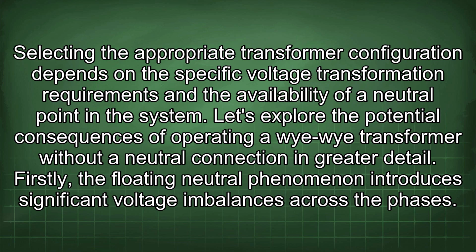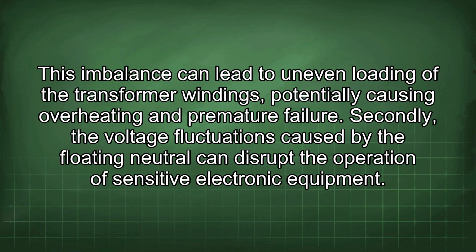Selecting the appropriate transformer configuration depends on the specific voltage transformation requirements and the availability of a neutral point in the system. Let's explore the potential consequences of operating a Wye-Wye transformer without a neutral connection in greater detail. Firstly, the floating neutral phenomenon introduces significant voltage imbalances across the phases. This imbalance can lead to uneven loading of the transformer windings, potentially causing overheating and premature failure.